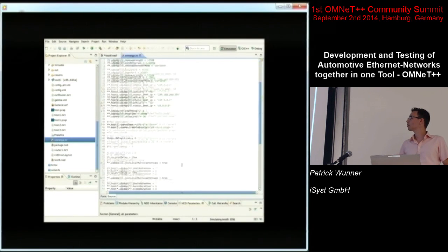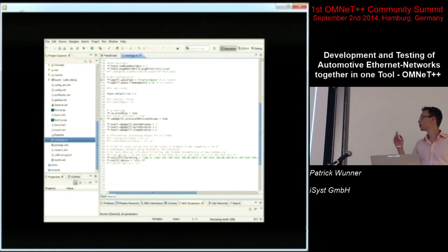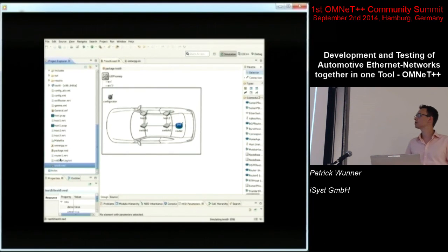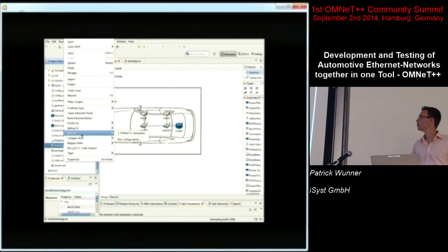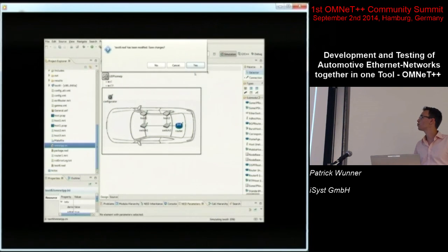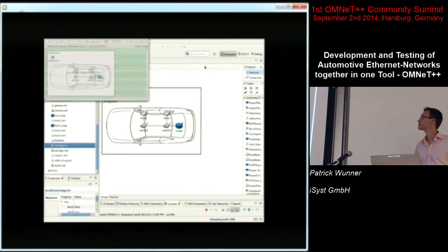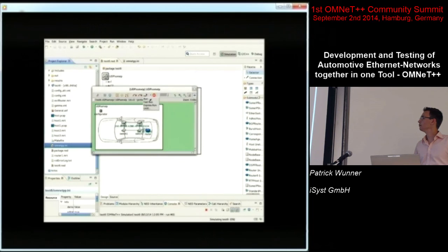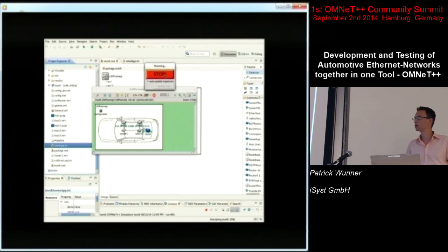Then the pcap recorder can be taken, and we have to define the filter string. The device here is eth1.73 for VLAN ID 73. And we have to do an express run because we need special timing for the rest-bus simulation to the external ECU.